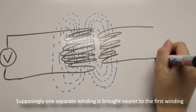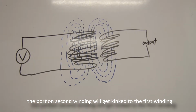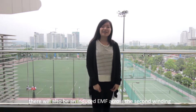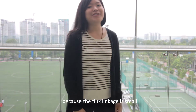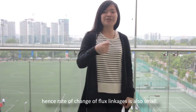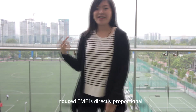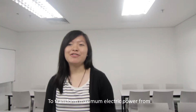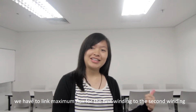Supposing one separate winding is brought nearer to the first winding, a portion of the second winding will get linked to the first winding. Due to this varying flux linkage, there will also be an induced EMF across the second winding. However, this induced EMF is small, because the flux linkage is small, hence the rate of change of flux linkage is also small. This is according to Faraday's law, where induced EMF is directly proportional to the rate of change of flux linkage. To transfer maximum electric power from the primary winding to the secondary winding, we have to link maximum flux from the first winding to the second winding.